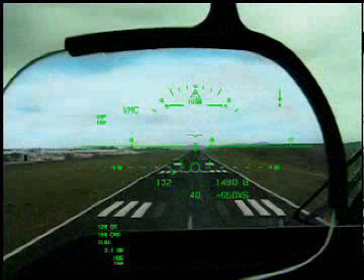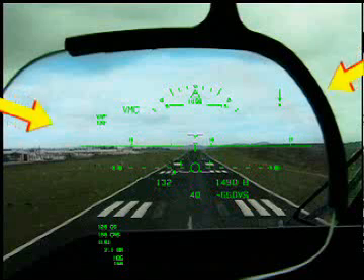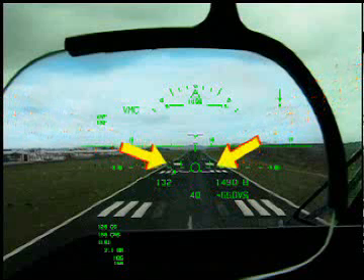However, navigation data is not displayed. Flare and landing in the VMC mode is accomplished using normal visual procedures. Between 55 feet and 10 feet, flare cue symbols consisting of 2 plus signs are displayed above the flight path symbol wings.